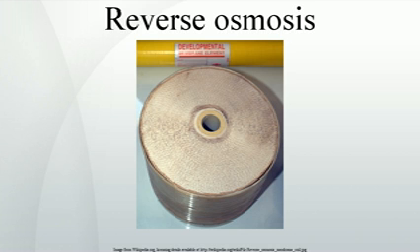Pre-filtration pH adjustment. If the pH, hardness and the alkalinity in the feed water result in a scaling tendency when they are concentrated in the reject stream, acid is dosed to maintain carbonates in their soluble carbonic acid form. Carbonic acid cannot combine with calcium to form calcium carbonate scale. Calcium carbonate scaling tendency is estimated using the Langelier saturation index. Adding too much sulfuric acid to control carbonate scales may result in calcium sulfate, barium sulfate, or strontium sulfate scale formation on the reverse osmosis membrane.